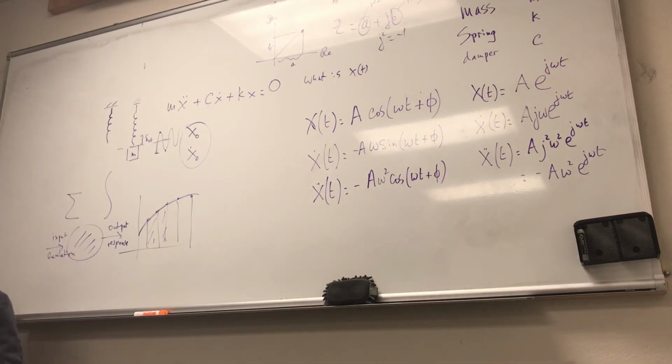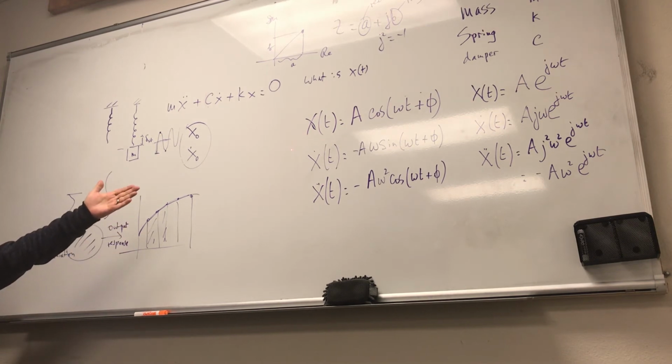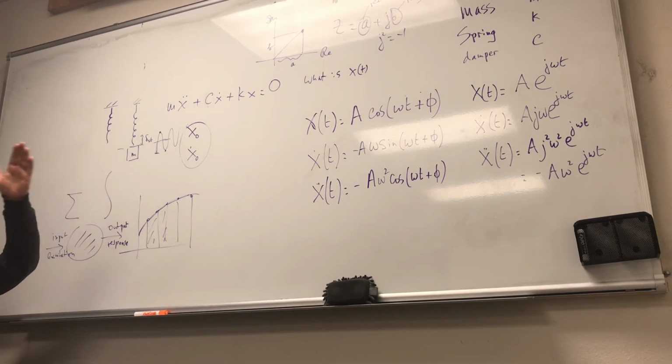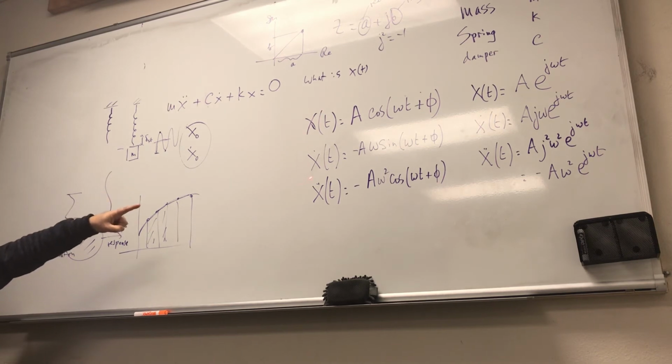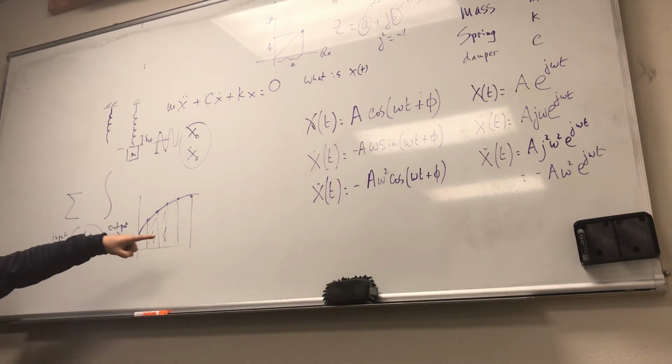Chain rule is very important in dynamics, and it's going to be important here. Okay, we were at interpreting results. So what did we say about interpretation of results? The solution of the governing equations gives displacements, that's what you're solving for. But it's your job to take that solution, take its derivative with respect to time to find the velocity response, and then take an additional derivative to find the acceleration.